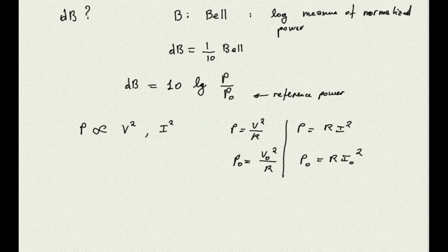Isn't that beautiful? We have the measurement of a magnitude that does not rely on the particular unit we are using, and also has a logarithmic value, so it is easy to represent large ranges on a diagram. The only thing is that we have to know what we are doing. When we use the power, we multiply the logarithm by 10, but when we use the voltage or current, we have a power of 2 inside the logarithm.